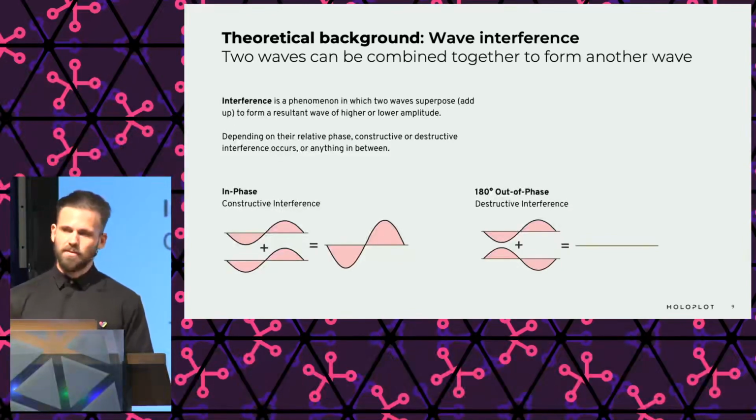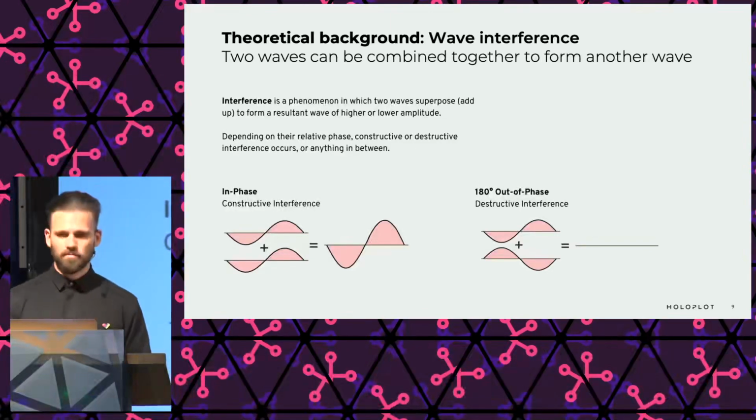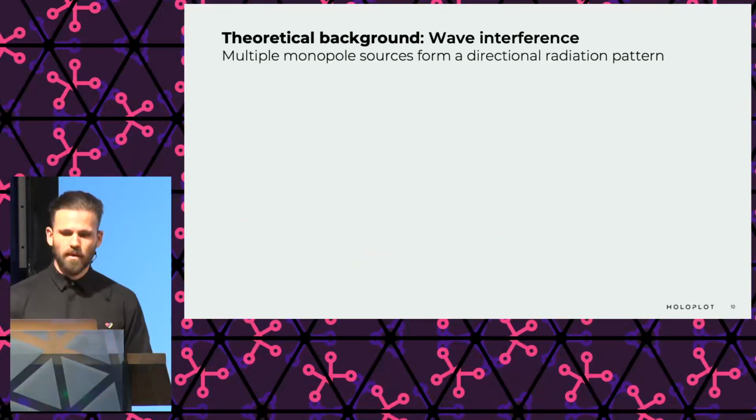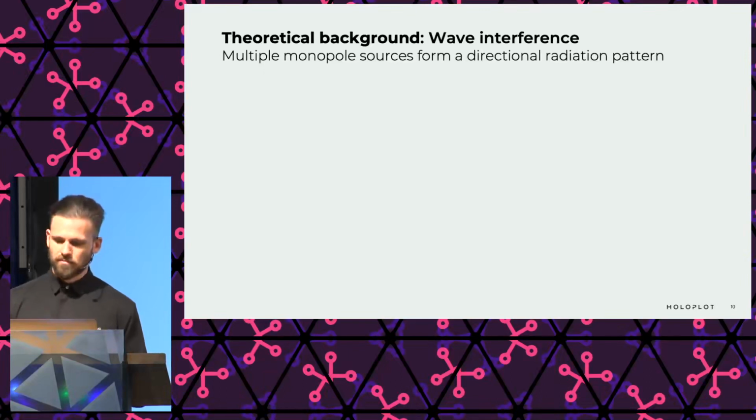Advanced loudspeaker arrays rely on the principle of controlled interference, which is based on the precise manipulation of phase between the loudspeakers built in the line array. A couple of slides before, remember we learned that a loudspeaker radiates differently for low, mid, and high frequencies. If we want to cause interference between several speakers in the array, we need to put them close enough so that the dispersion patterns overlap physically and they can accordingly interfere with each other.